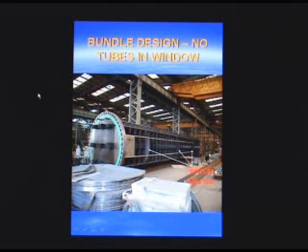This is an example of baffle plates for eight of these exchangers that were fabricated, all with no tubes in window. This shows only partial tube bundle because this was pushed into a shell and then the tube sheet was put on the far end once the bundle had been inserted. So here's a baffle which shows the window closure here. These are segmental baffles or intermediate support plate baffles down here, which basically allows you to reduce the unsupported